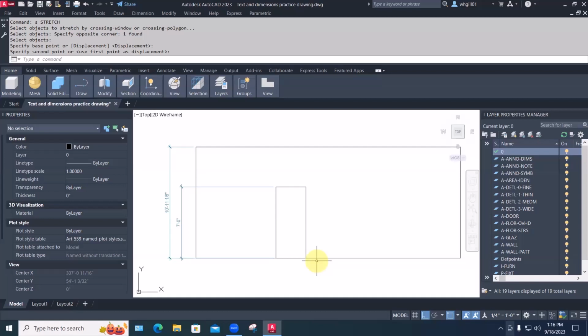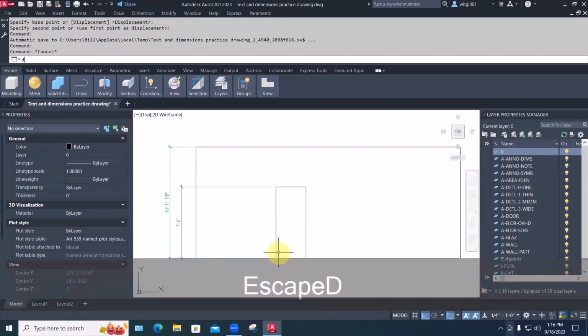And that's how we need to dimension them, because if I say I need a 33 3/4-inch door, the door guy will think, oh, a custom door, and charge extra. Only a couple of times would there be a 33-inch door, if you've got double doors on some closet that can't change, and then that would be a custom door. But pretty much all of these we want to draw at the full 36.